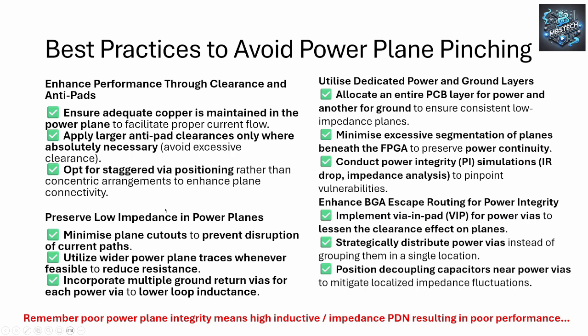Okay, so best practices to avoid power plane pinching. I'm not going to go through this. All I'm going to say is remember power plane integrity means high inductive, high impedance PDN, and that results in poor performance. The other thing I would say is it doesn't matter how much decoupling you throw at an FPGA or a chip.